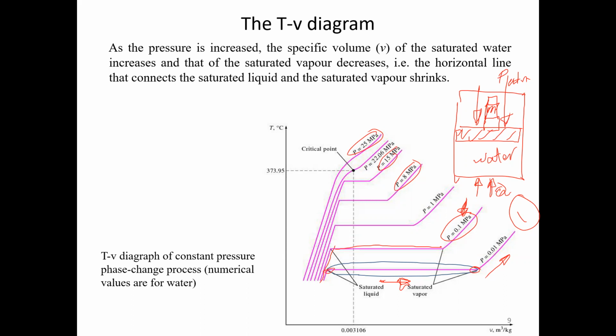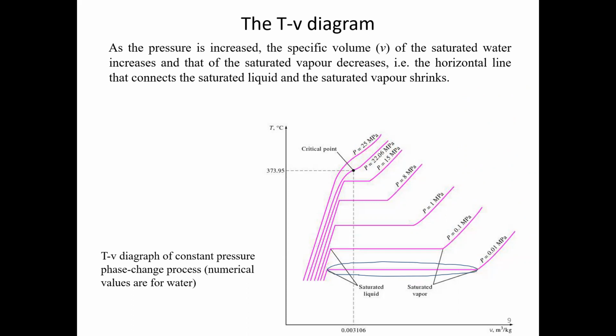Why are we doing this now? If you have a look at the graph here, the first pressure line has this amount of latent heat. You can see, because we said the starting boiling point here, that we change some of the water to vapor until we reach the other side where we change the whole water to vapor. Between them, we call it latent heat, correct?